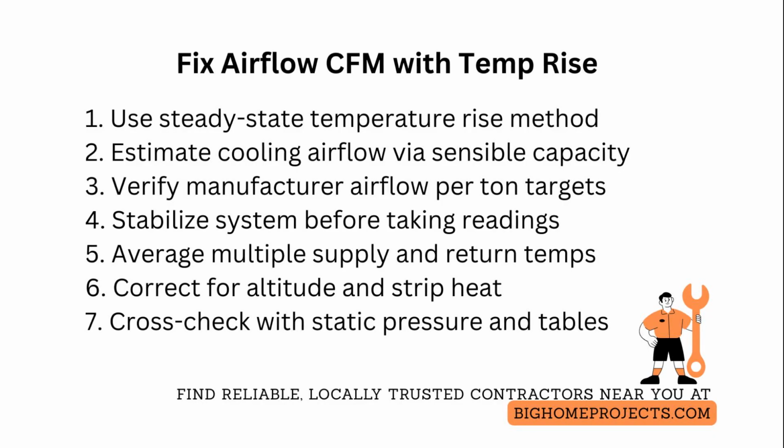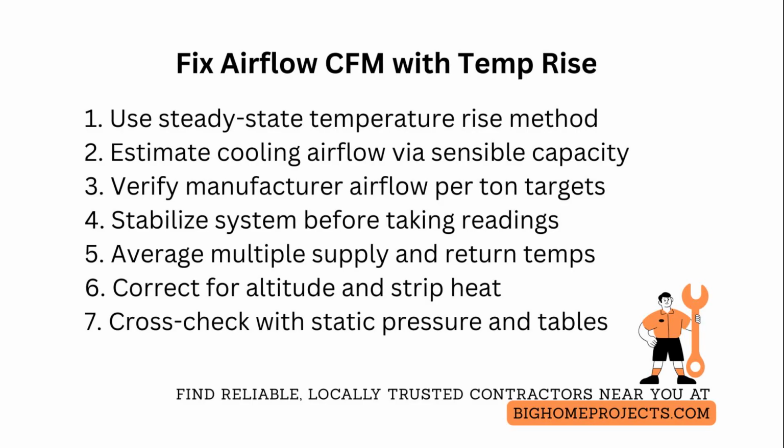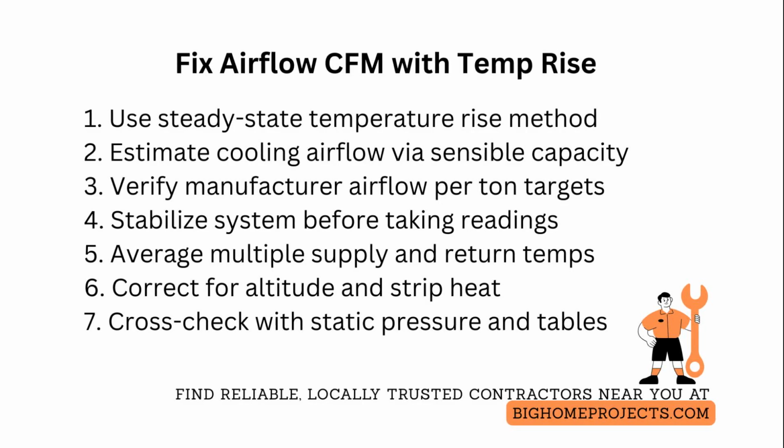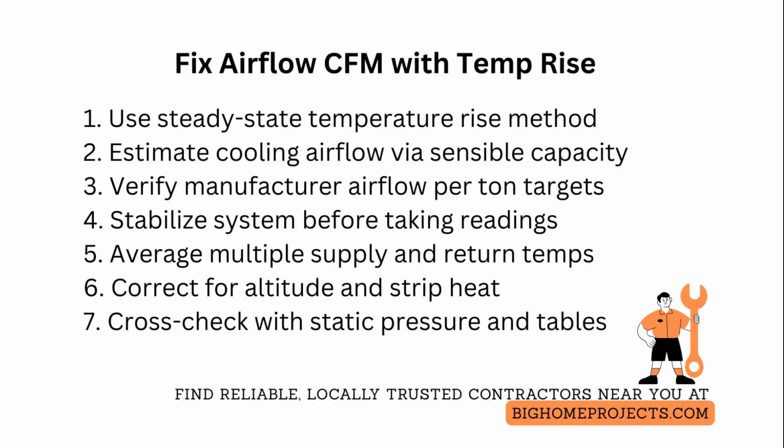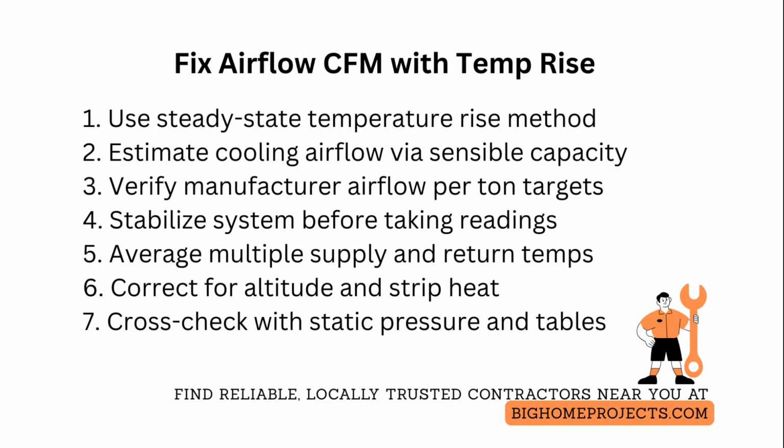Cross-check airflow with total external static pressure plus the blower performance table. Do not trust temperature alone when coils are partially wet or dirty. Document line voltage, blower tap or percent, filter model, coil cleanliness, and damper positions, so your airflow calculation is reproducible.